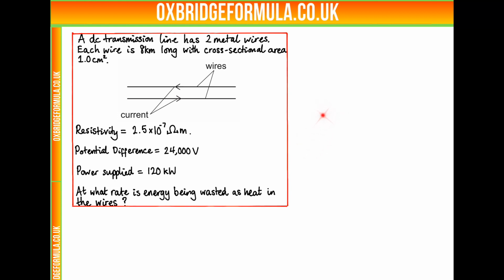And this is because, in a similar vein to internal resistance, these wires take a fraction of the power that we're putting in. So this resistance is associated with the wires, and so they'll take a certain potential, which is IR, not the whole potential 24,000, but a certain potential V, dissipation times the current going through them. So the equation we should use is P dissipated is I squared R, where R is the resistance of the wires.